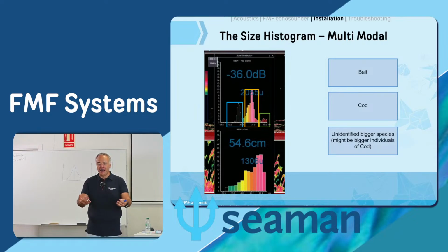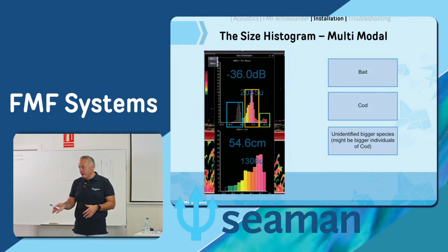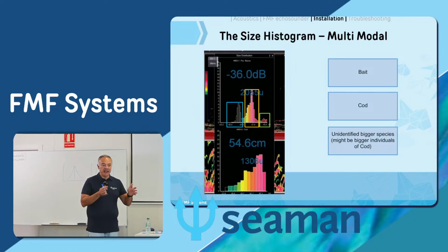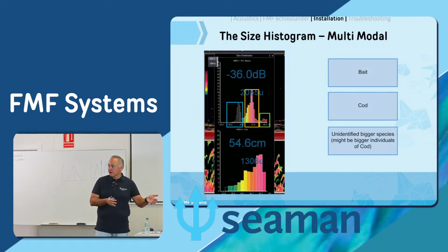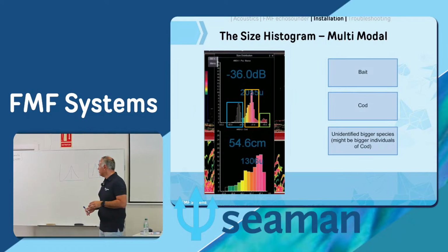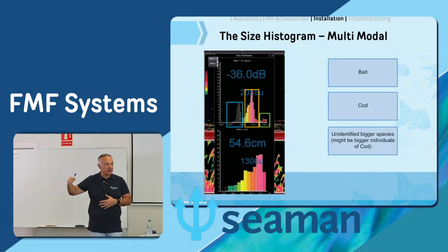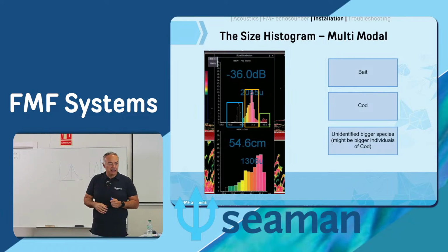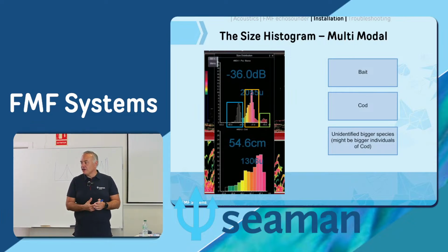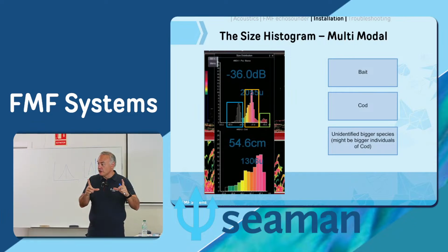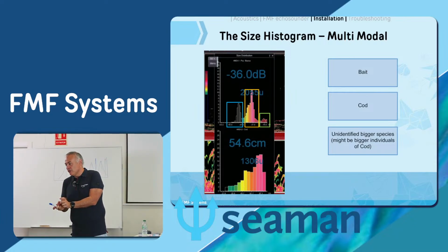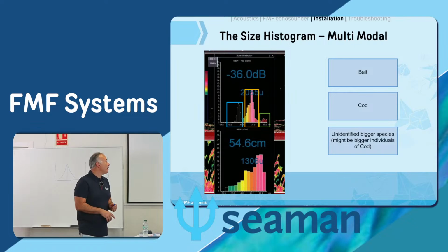So when you offer a client a target measurement solution, please keep in mind that if it is a 1000, a split beam sounder, it will have all the features included, the vertical lines, the species. And if you offer a 900, then it will be like a normal 900 with a size indication. We have only one histogram, the vertical lines, and then you can add the specific species formula package.